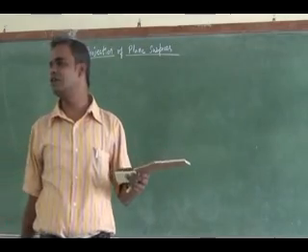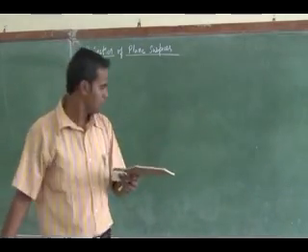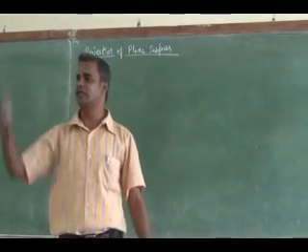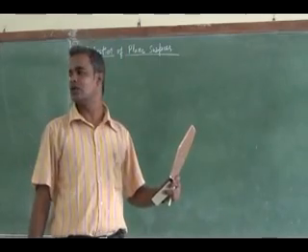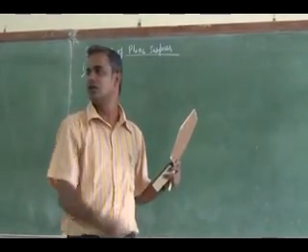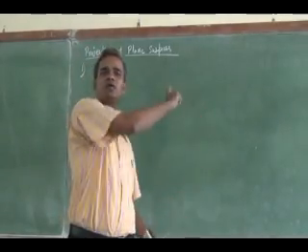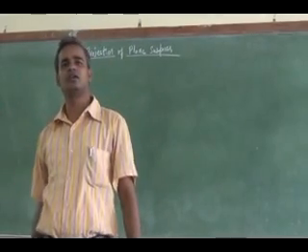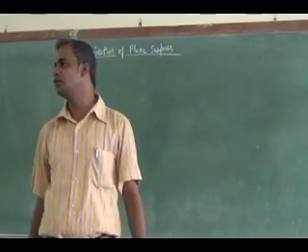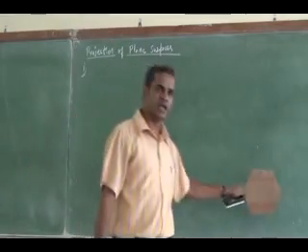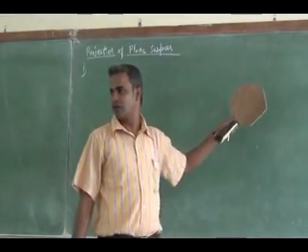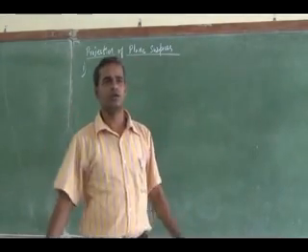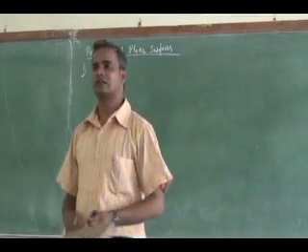That is the final front view length I will obtain in this first assumption. Then that front view will be tilted to this orientation, the true inclination to the horizontal plane. That is going to be my final front view. Then the final top view will be obtained by projecting this final front view and getting the projectors from the previous top view. So I will end up with the final top view.